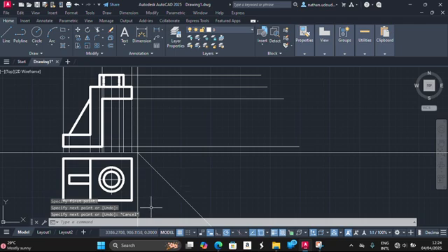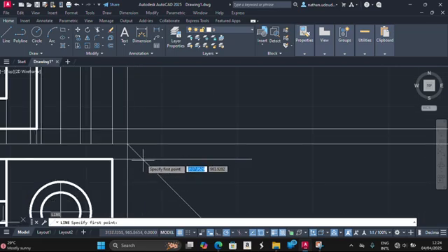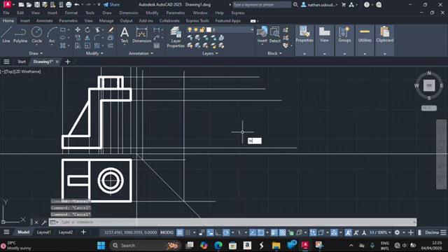and then I can also project lines from my plan. So let it meet the inclined line, L enter again. So now from this point of intersection with the inclined line, you left click, L, and then you drag, you move upward with your line command. So the same thing, L enter, you left click here, and then you move upward, and then escape. So now you can trim up, TR, enter.